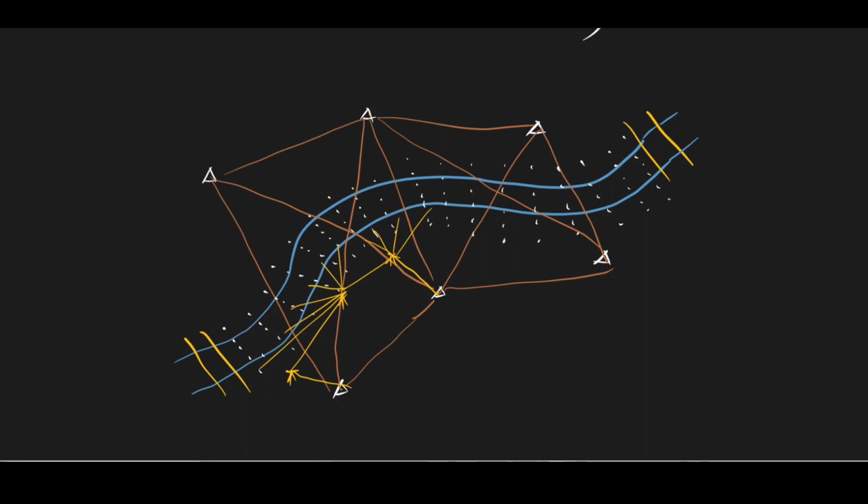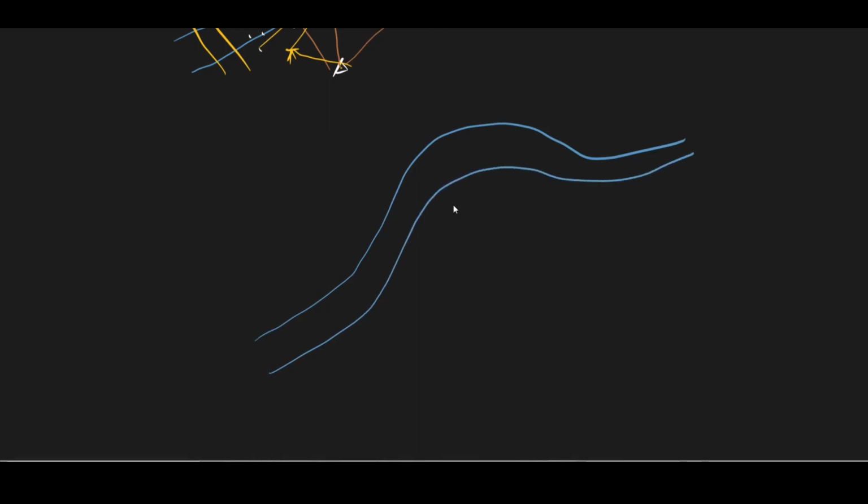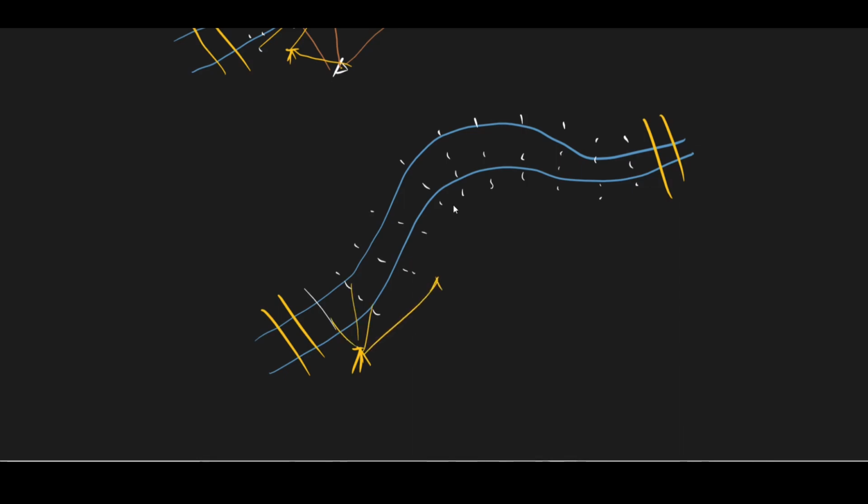So let's say you didn't establish your points. So let's draw another scenario right here where you didn't establish control points in the first place. Okay, so let's say you started with a traverse right here, and then you observed, and then you continued on. Let's do the cross sections. So you observed here, and then you moved here, and then you observed here again, then like that, and then you moved here, turning points, and then you moved here again, and then you moved here, then you crossed the river to observe this side.